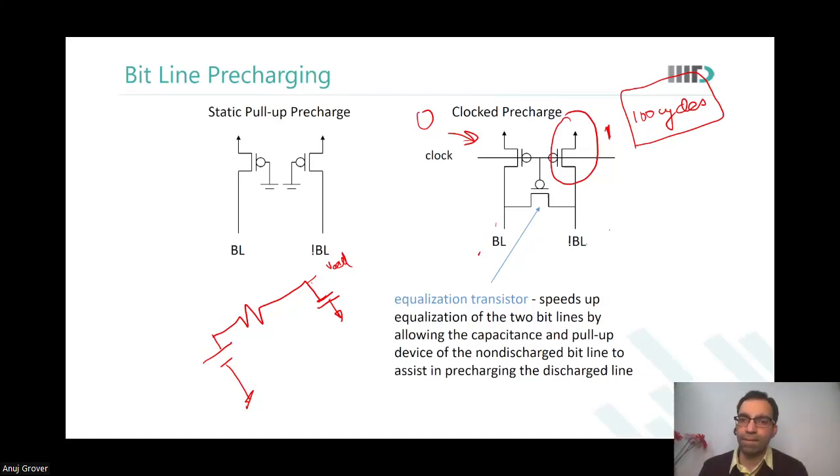Is it used only before the read cycle? Because in write, we are supposed to make our bitline high and bitline bar low, right? So in that case, if we give this clock, then both the bit lines will be high, having the same value. But in a write cycle, one should be at VDD and the other at ground, right? So this clock should go off even during the write cycle? Yes, sir. That was my doubt actually.